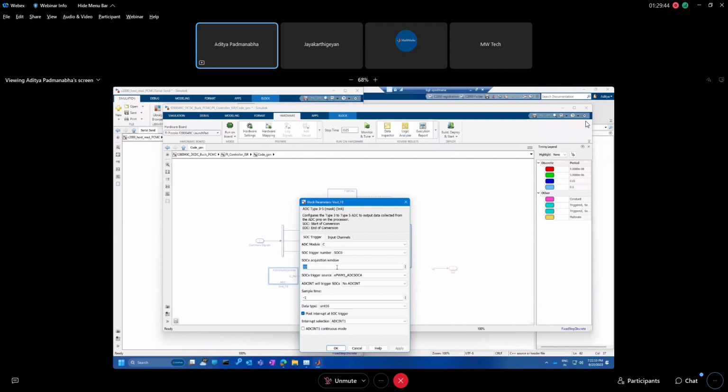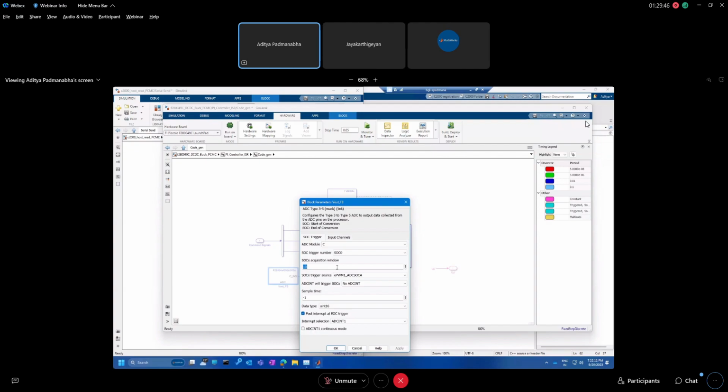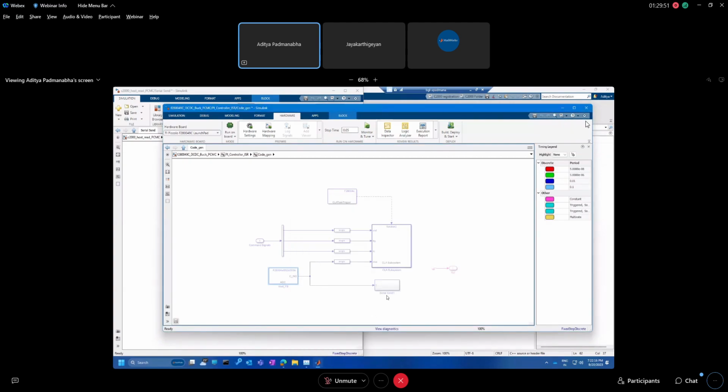That itself acts like a filter, but on top of it you can implement additional filtering mechanisms. For example, you can implement an IIR filter which filters the ADC, and use that filtered value to run the PI controller.